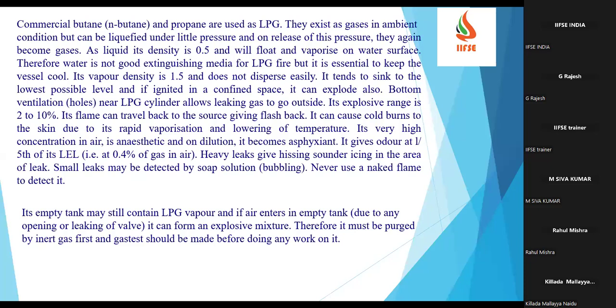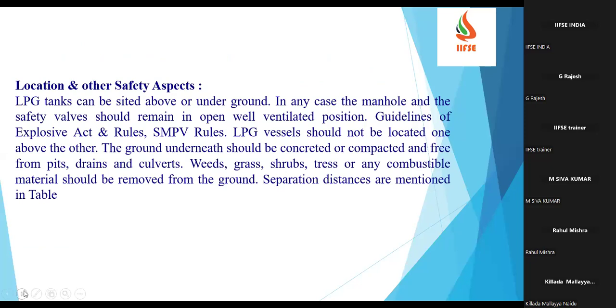Therefore, it must be purged with inert gas first, and a gas test should also be made before doing any work. Nitrogen, helium, argon or other inert gases can be used for purging, in the sense we have to supply it inside so that it replaces the oxygen or other gases inside. Then we can start the work on that specific container. And if you see the location and other safety aspects, LPG tanks can be sited above or under the ground.